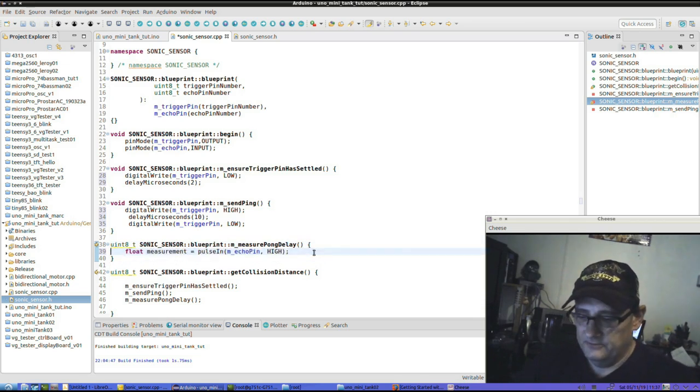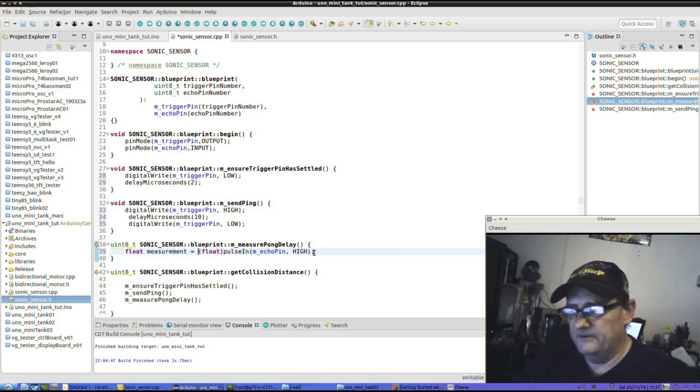So there's no reason to put redundancy in there. And if you did leave it in there, I found out that every once in a while, when you look at the raw assembly language code for some of this stuff, and I've done a lot of that, this forcibly converts the result into a float before it assigns the variable. It'll convert it, store it, and then check to see if it's floating, and so it just adds code. Sometimes it does, sometimes it doesn't. So I omit it. I say the compiler's smart enough to figure that out.